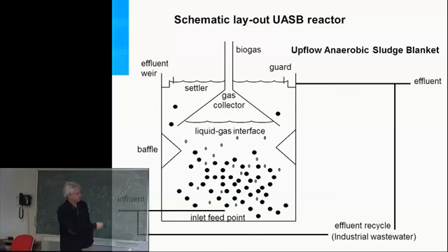So this part is quite turbulent. You have biogas production with a lot of sludge. Here you have a kind of interceptor where the biogas is entrapped. This means that there is no biogas and no turbulence at the top part of the reactor, so all the sludge that comes to the top part can settle and slide back into the system. In fact, it's a bioreactor with a secondary clarifier combined. At the bottom you have the bioreactor, and at the top part you have the secondary clarifier.